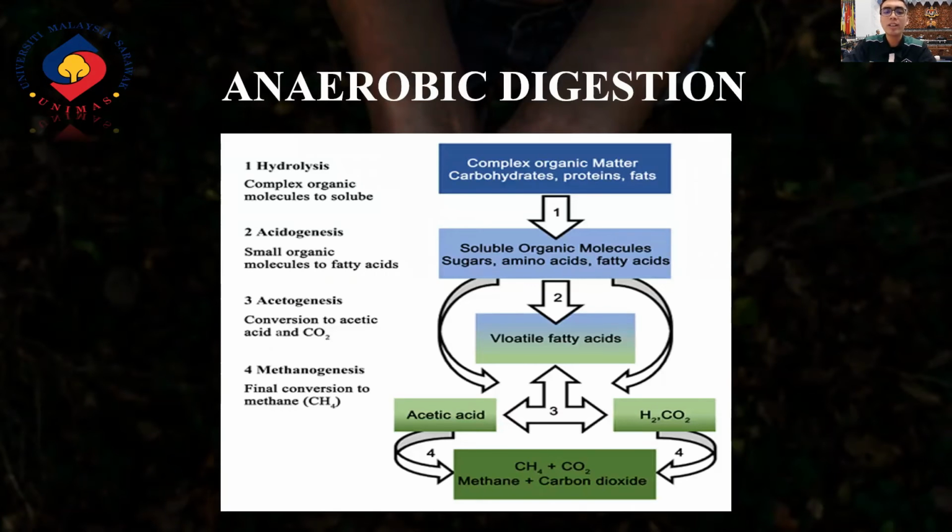And then we have anaerobic digestion. So anaerobic digestion is a biological process that is highly reliant on the existence of a favorable environment and condition to sustain the metabolism. Anaerobic digestion is a complex process in which bacteria from different functional groups collaborate and degrade various organic compounds in order to produce methane and carbon dioxide, CH4 and CO2. Numerous factors including the digester's design, feedstock, temperature, and other parameters may affect the organization of the microbial population. So from the figure on the screen, here are the processes that happen in the anaerobic digestion.